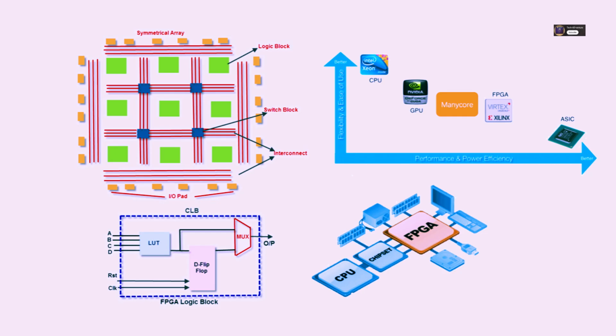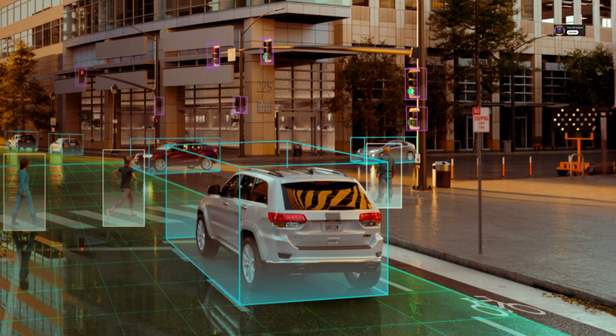Yeah. Okay, so let's use the autonomous car as the ultimate example. We need all these parts, right? So the GPU is doing the heavy lifting on deep learning object detection, and the CPU is managing the overall driving decisions. Where does that low latency deterministic FPGA fit? It often fits right at the edge, close to the sensors. Imagine the raw data flooding in from LiDAR or radar sensors. That data stream might need ultra-fast processing, filtering, maybe some specific digital signal processing before it even gets passed to the GPU for the complex AI recognition.